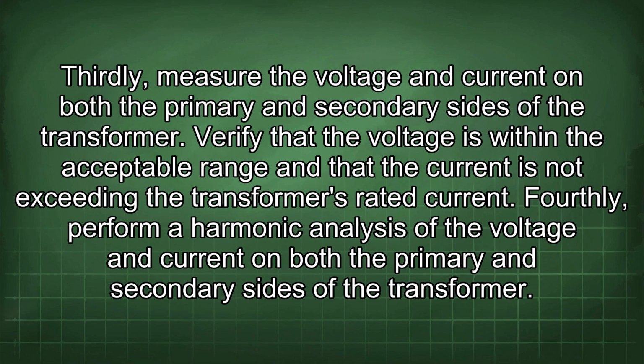Thirdly, measure the voltage and current on both the primary and secondary sides of the transformer. Verify that the voltage is within the acceptable range and that the current is not exceeding the transformer's rated current.